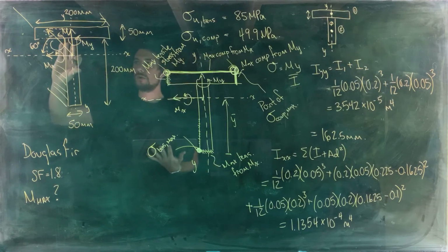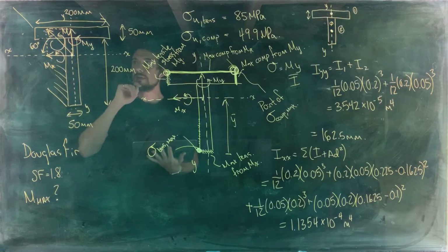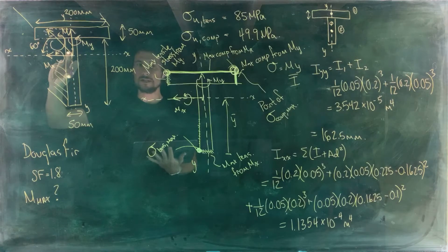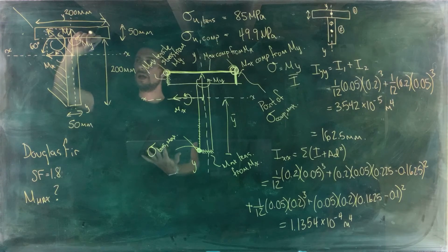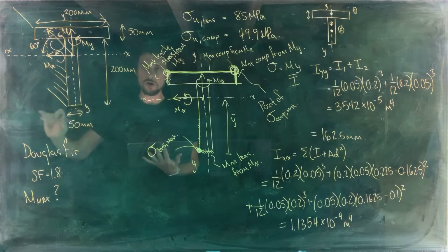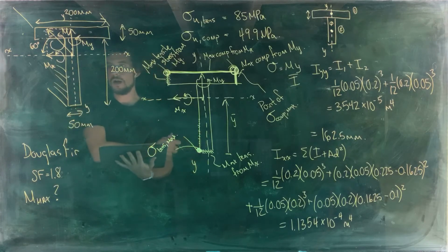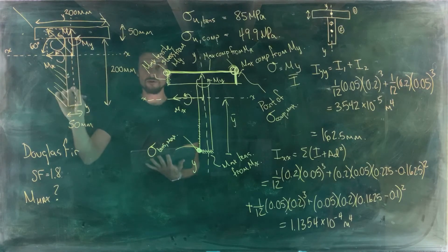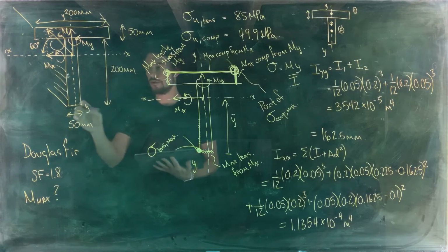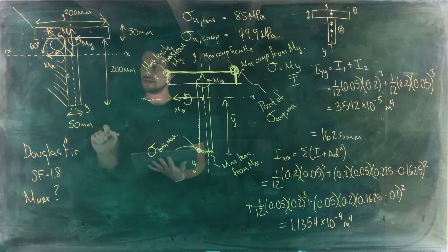If we wanted to strengthen just the vertical piece here, then we might be able to get away with having something that's as strong as we need just by taking one additional piece of wood and putting it on the top to create the top of the T without also adding one at the bottom. Maybe we could make an I-beam and make all of the wood smaller dimensions, right? So we'd have less wood overall and have that satisfy our need.